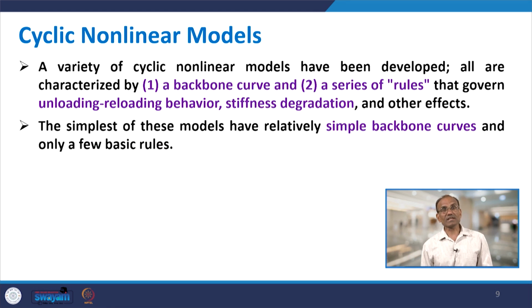A variety of cyclic nonlinear models have been developed. All are characterized by two things. One is called the backbone curve and a series of rules that govern unloading reloading behavior, stiffness degradation and other effects. So, these cyclic nonlinear models deal with two things.